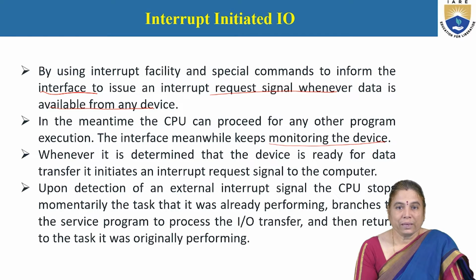But in the previous case, programmed I/O, where an I/O instruction originates the transfer from the program, the CPU must continuously monitor the status of the input-output operation. In interrupt initiated I/O, the I/O interface monitors the I/O operation completion and the CPU can continue the program execution.